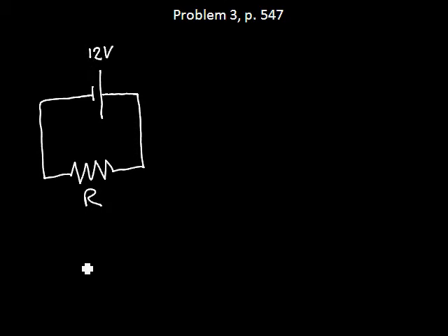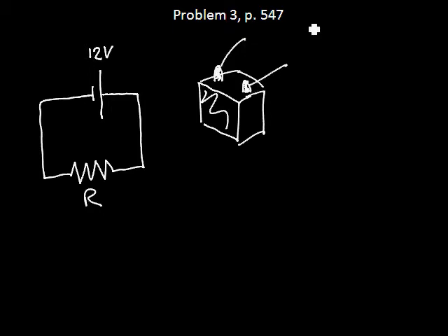Okay, well, the current that flows through the external circuit also has to flow through the battery. And a real battery is going to provide some resistance to the current that has to flow through it, the internal resistance. So if we think about a car battery and what it looks like, it's a box, and sticking out the top of the box are two metal poles like that, and these are the terminals of the battery. They're connected to big thick wires that send electricity off to the starter motor, the car headlights, the radio, all the electronics in the car.